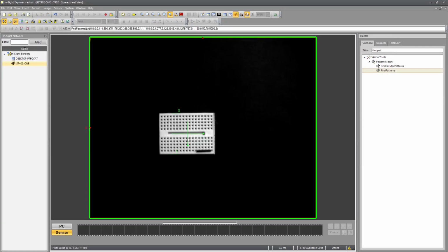So what this does is it looks for features on here that give it a unique orientation. In this case, we found this slot. Now, the problem that we're going to have is that if our control piece here has some surface defect, just searching for this may not actually yield the result we want.